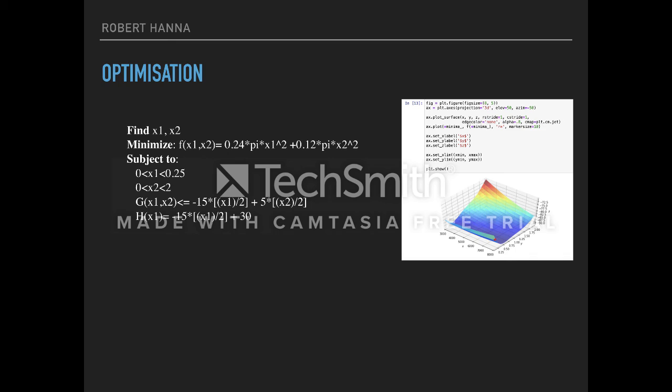So here's just a high-level thought experiment, just to touch on what we talked about with optimization in class. Here's a little plot I made in Python of a situation where we might want to minimize the weight of both the capstan and the knobs given a few constraints. So, dimensionality constraints on the capstan diameter and the knob diameter. The capstan can't be more than 1/4 inch, say, because that would be pretty large itself, and the knob can't be more than 2 inches in diameter, which would be relatively large as well, but just for the sake of showing it here.